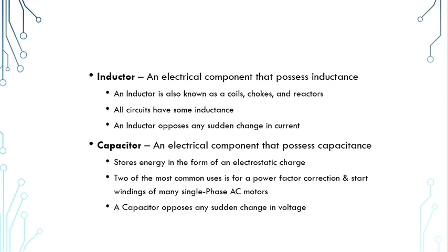Single-phase here in the continental United States would be 120 volts nominal and 240 volts nominal. Now, because they work off of magnetic inductance to get these motors to start and run, it's hard to get them to start because their poles, depending on where they are in rotation when they shut down, might not have a very good magnetic pull to get them turning. So we'll use those capacitors to give us that 90 degree phase shift to help get it started in its rotation. Sometimes we use it to keep them running.